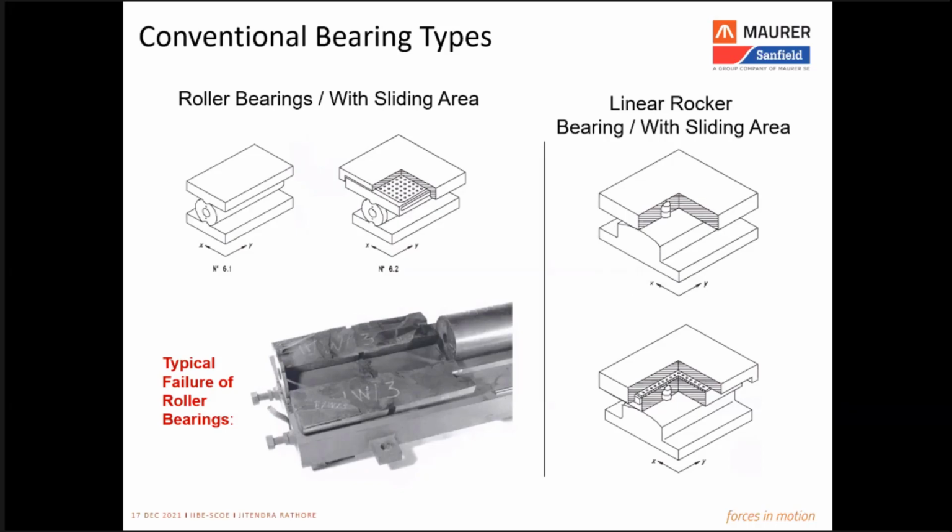If we talk about the conventional steel bearings, and you can look at this image, because of the continuous long roller length, this bearing can offer movement in the longitudinal direction. It can also offer rotation about the transverse axis of the bearing. That means if the girder is sagging due to live load, it can take that rotation.